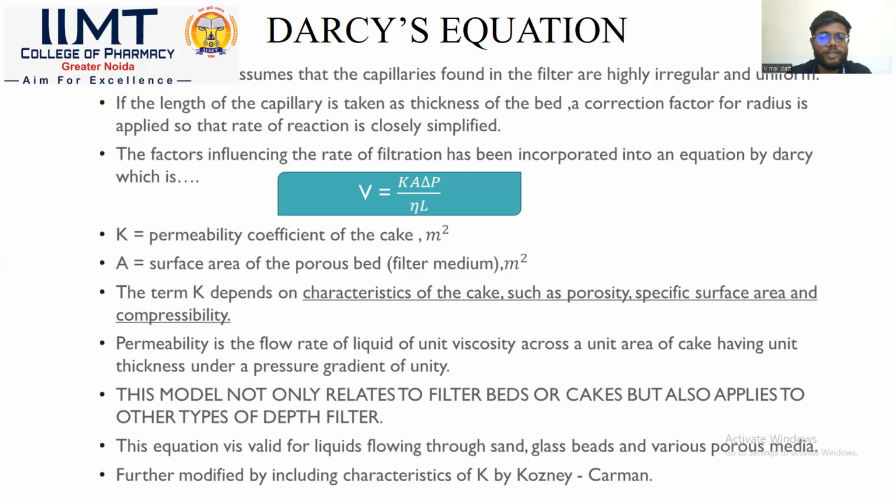Permeability is the flow rate of liquid of unit viscosity across a unit area of cake having unit thickness under a pressure gradient of unity. This model not only relates to filter beds or cakes, but also applies to other types of depth filter. This equation is valid for liquids flowing through sand, glass beds, and various porous media.